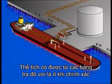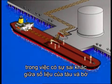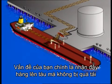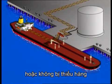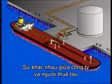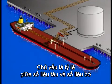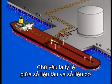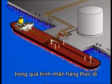The volumes given by the ullage tables are seldom exact. When you load the vessel, you will, most of the time, experience differences between your own figures and shore figures. Your problem is to take on board a full cargo without overloading nor short-loading the vessel. To be able to do this, you must know the vessel's experience factor. Different companies and charterers use slightly different methods to compute this factor. Principally, it is the ratio between ship's and shore figures obtained by comparing the results of a number of actual loading operations.